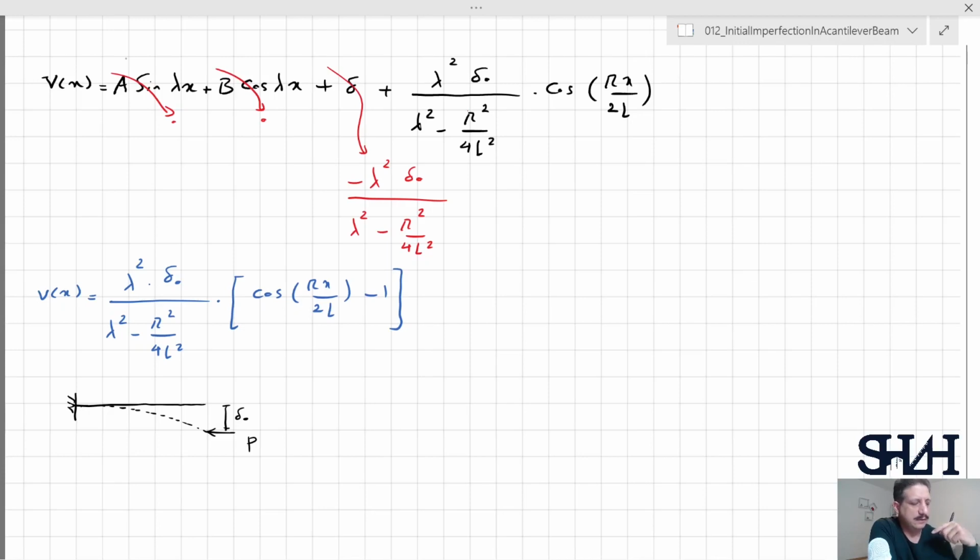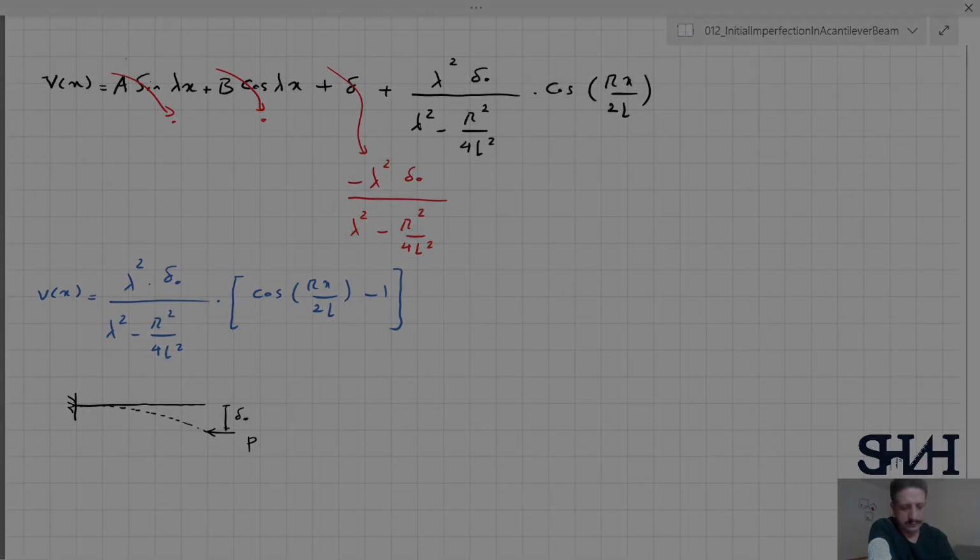The stress is a combination of the axial force, which is compressive here with the value of P, and the bending moment. If we increase the load, then it will deform more, and with more deformation, we have more bending moment at the support.